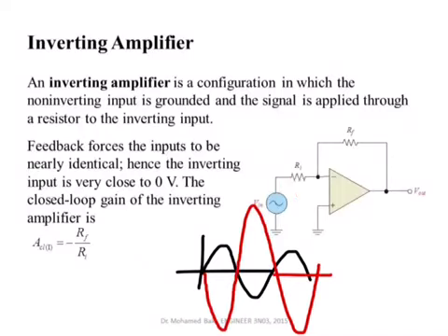And the reason for that is that if you short the input, and then connect a current source at the output here, we call it Ix. This is the way we determine the output resistance. Short the input, remove the input, and then connect a current source, and then try to determine the voltage drop across this current source. And this voltage drop will tell you what is the resistance seen from the output of this amplifier.